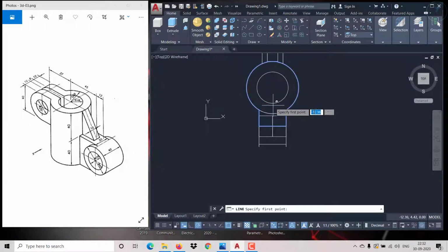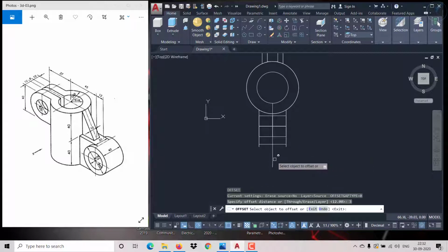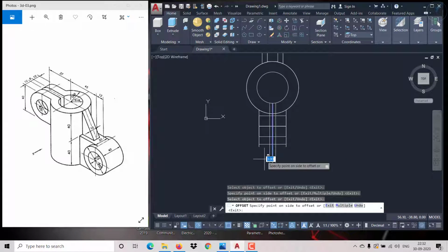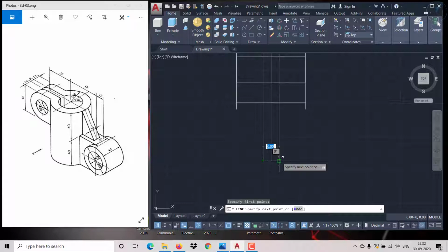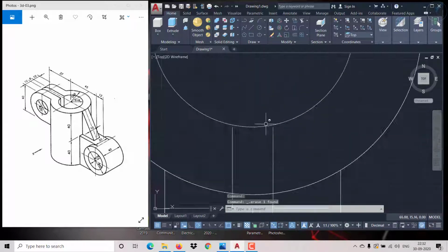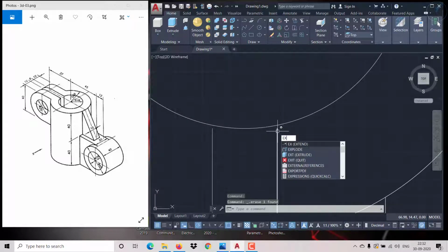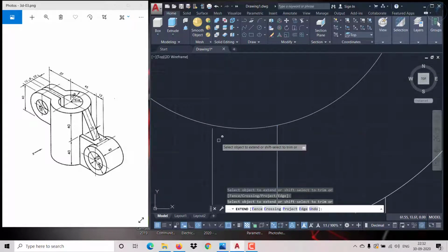So now we need to make this over here. So I'm just creating lines exactly on that quadrant straight up to after the solid over. So now I just make offset of 3 mm over here and 3 mm over here. So now you can join this endpoint by using a line, and now you can delete the center, we don't require that. So then extend it, EX, double time enter up to here, then hold shift to trim the middle